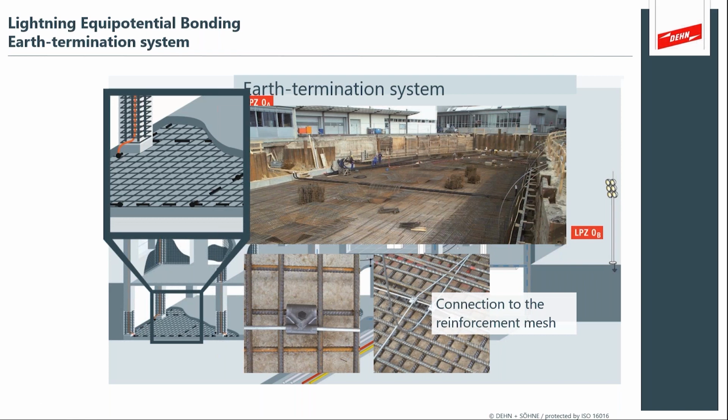And along with corrosion and water ingress, the simple fact that lightning might be hitting your concrete support members is going to induce premature failure if it's not bonded together, equipotentially bonded throughout that mesh of rebar. And this is really important because if it's loosely connected, it could be arcy and sparky on the inside.